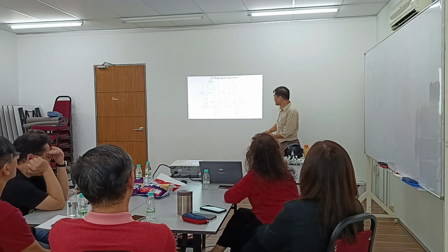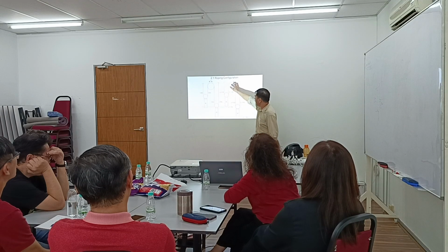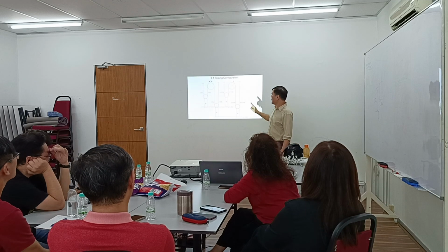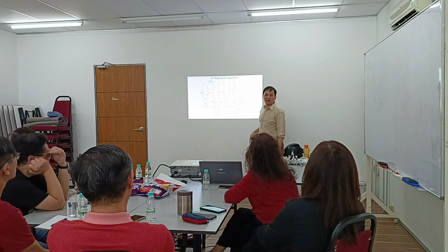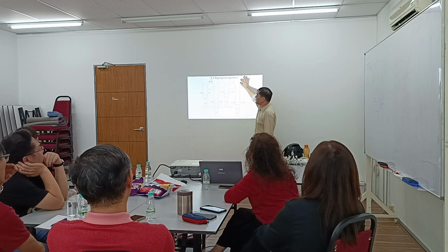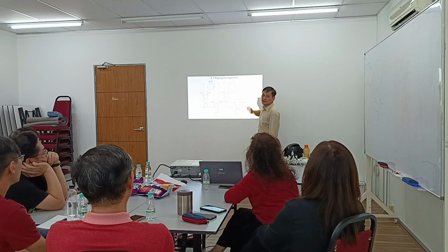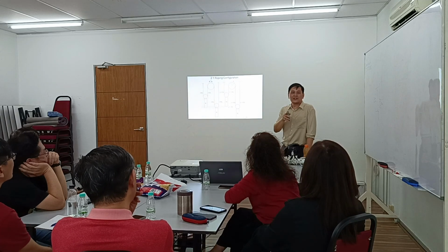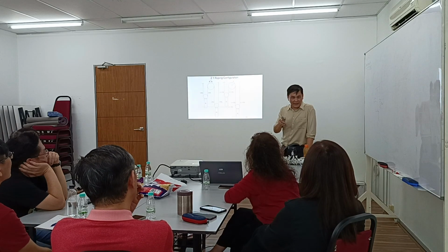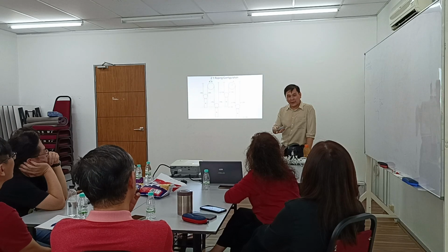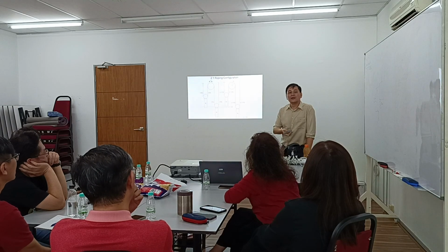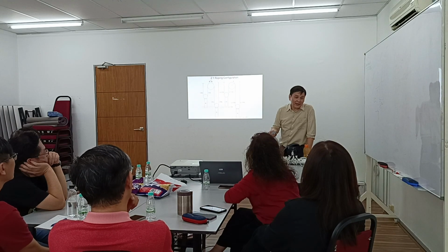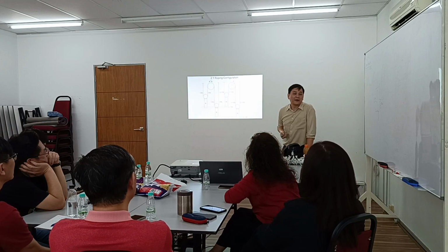So when the shaft moves, the rope only moves half of the movement. But the good thing is it can take double the load, because another load is actually taken up by here. So for a 1000 kilogram motor with a speed of 2 meters per second, when you apply 2-to-1 looping, it can take 2000 kilogram, but the speed will be reduced to 1 meter per second. This is usually how we play around.